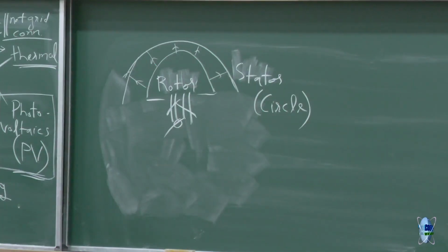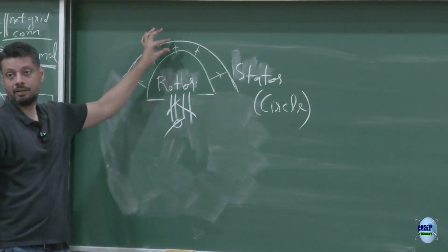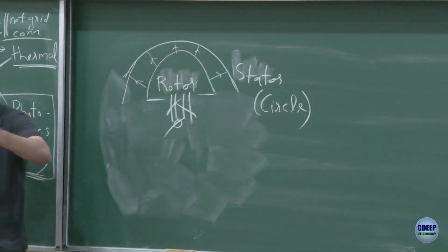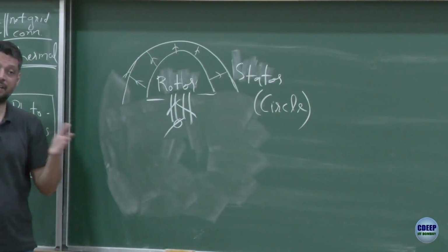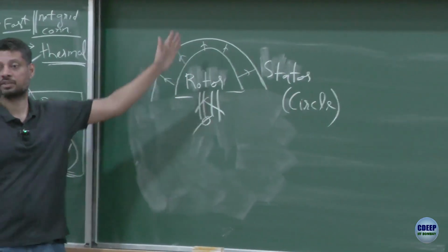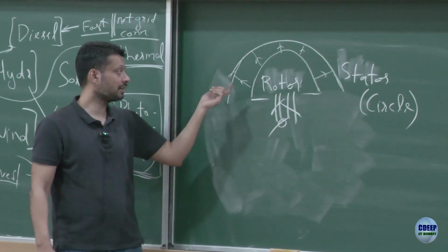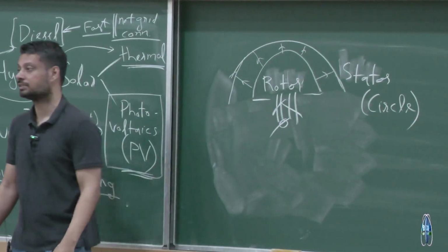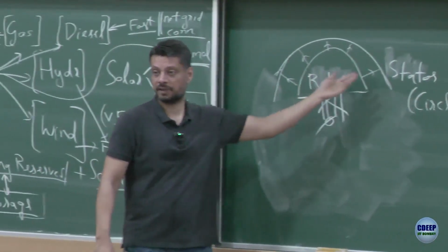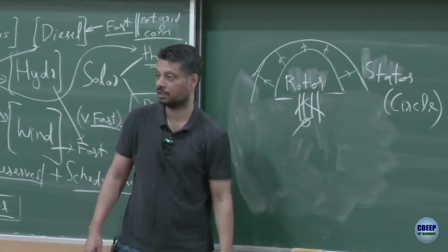No, right? Because here reluctance is small, less, because of lesser length of air gap. Here there is a larger length of air gap, so reluctance is more. A smaller air gap means more flux will flow through it. A larger gap means lesser flux will flow through it. Is that okay?